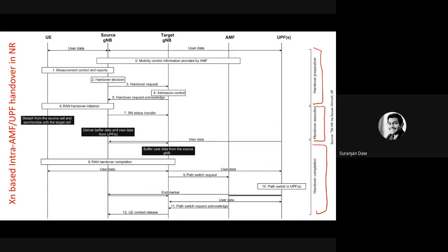The request is being sent to one of the identified cells. Yes. During the handover decision, it may look at the information related to multiple neighboring base stations. Finally, it has decided that so and so base station is the one to which I should hand over the user. So that is the target gNodeB. And by keeping the identifier of the target gNodeB, in this case the cell identifier, we send the handover request.